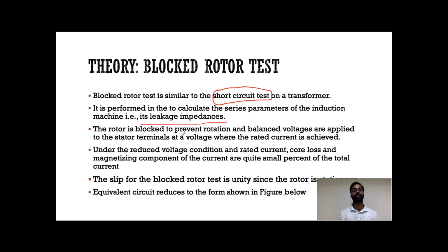You should note very carefully that the voltage should be increased only up to the level where the current flowing in the winding reaches the rated value. If you increase the voltage more than that, it may damage the winding, because a huge amount of current will flow, just like a short circuit condition, and it will be very harmful for our experiment, and the meters will be burnt.